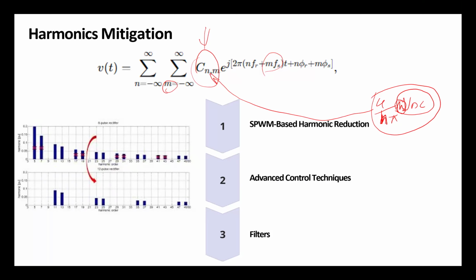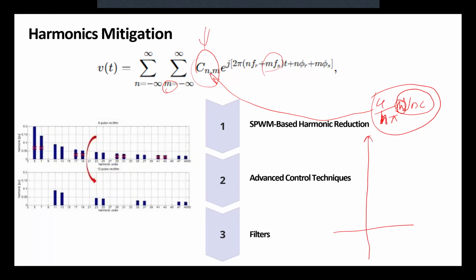Same goes if you remember we had a graph where we said if we have a switch 1 and it's cutting off with a duty ratio this way, we could represent switch 4, which is the complement of that switch 1, and represent the overall with a value of 2D minus 1 as our modulation index for the whole system.